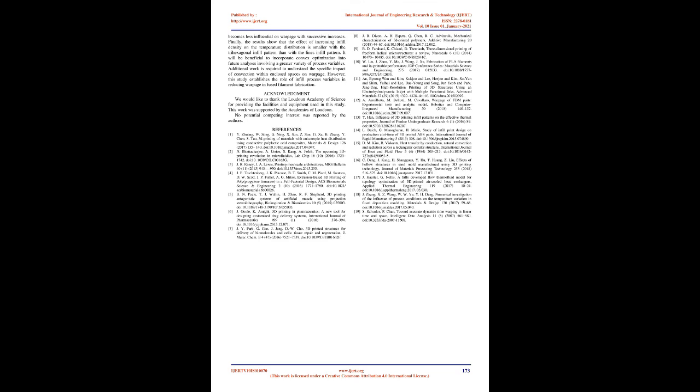In addition, 30% infill density is recommended in order to reduce warpage and promote part strength, but 10% infill density is still a viable option if cost is an important factor. The results also support that with increase in infill density, the effect of the choice of infill pattern on warpage reduces significantly, and that increasing infill density becomes less influential on warpage with successive increases. Finally, the results show that the effect of increasing infill density on the temperature distribution is smaller with the trihexagonal infill pattern than with the lines infill pattern.